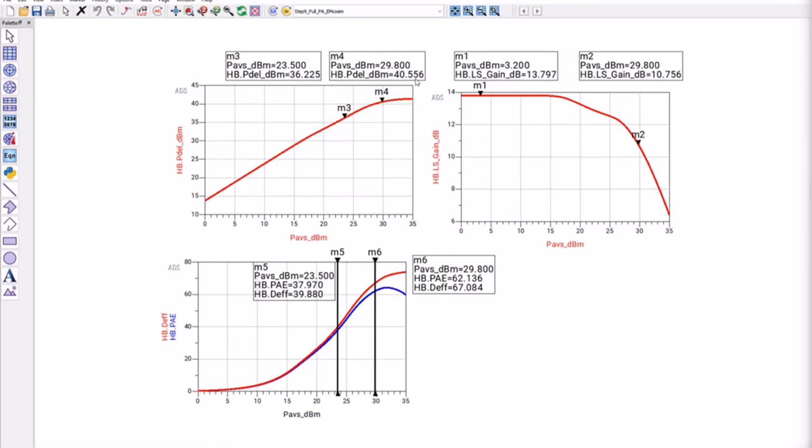So you still have a little bit of margin, but this is a little closer to what I would like to have. At this point, I would like to have 41 dBm, because remember, I still have two SMA connectors, which are not accounted for in this output power. And depending upon which connector vendor you use, you will have a certain amount of loss, plus some extra margin for PCB fabrication errors and so on and so forth.